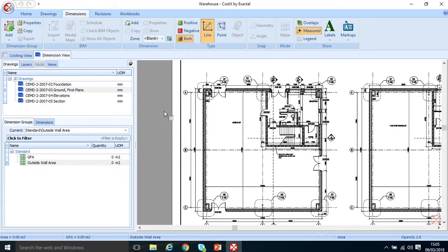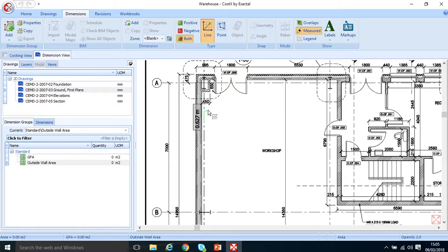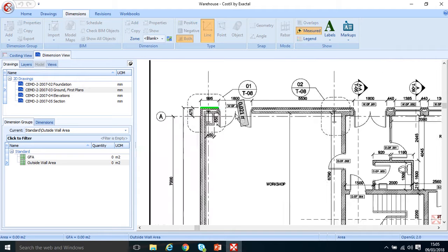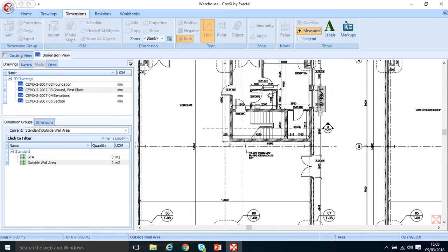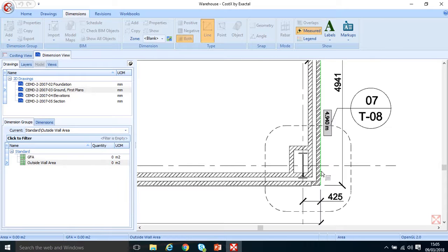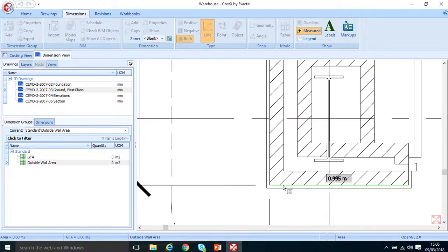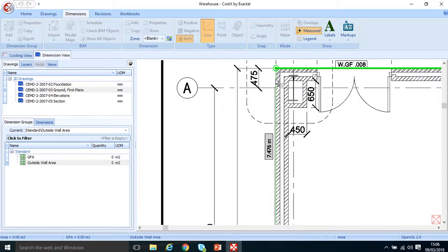Okay, so just to finish off this tutorial, I'm going to do a quick bit of measurement in dimensions. I can either measure in line mode or in point mode. We'll get to the difference between the two further on. So let me start. I'm going to click on a corner on one of the outside lines. I usually go from corner to corner, click again, and then come down to this corner, making sure I'm clicking on the right line, scroll in, click, and then come back to my first point and click.